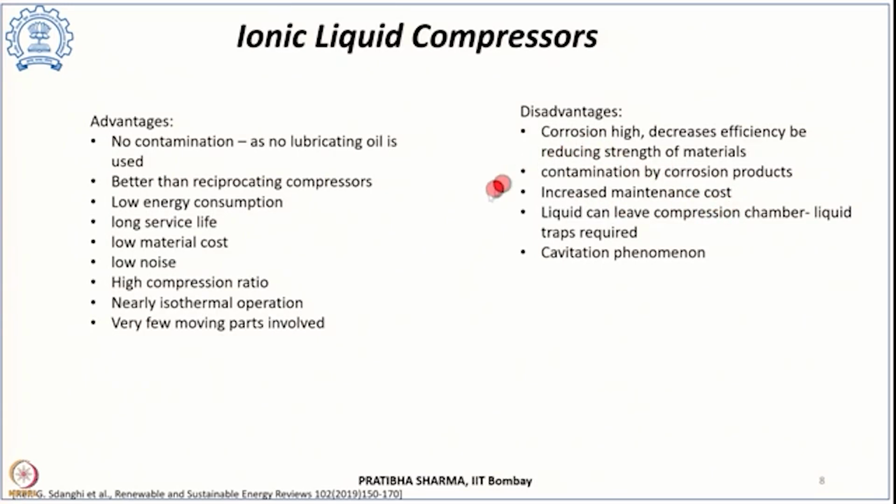At the same time, since the liquid and gas are present in the compression chamber, at times this liquid can also come along at the time of discharge. So, this liquid can leave the compression chamber, and to remove the liquid which comes along with the gas, we need to have liquid traps to separate it from the gas.